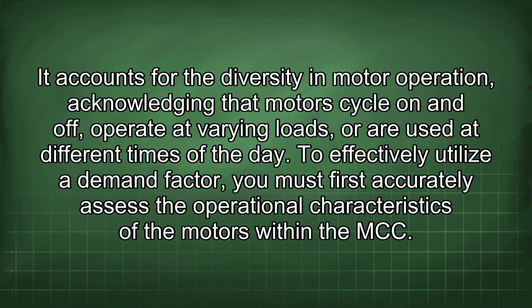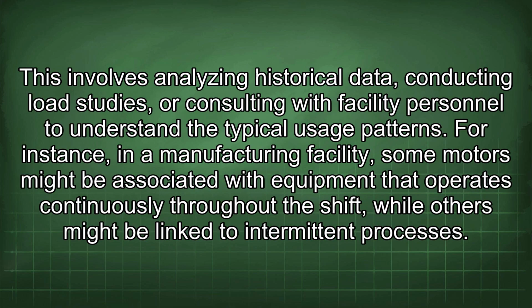To effectively utilize a demand factor, you must first accurately assess the operational characteristics of the motors within the MCC. This involves analyzing historical data, conducting load studies, or consulting with facility personnel to understand the typical usage patterns. For instance, in a manufacturing facility, some motors might be associated with equipment that operates continuously throughout the shift, while others might be linked to intermittent processes.